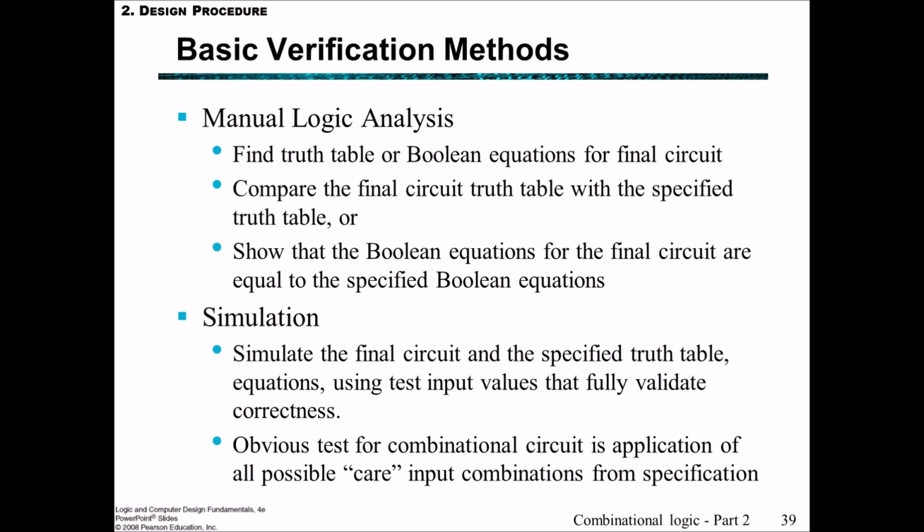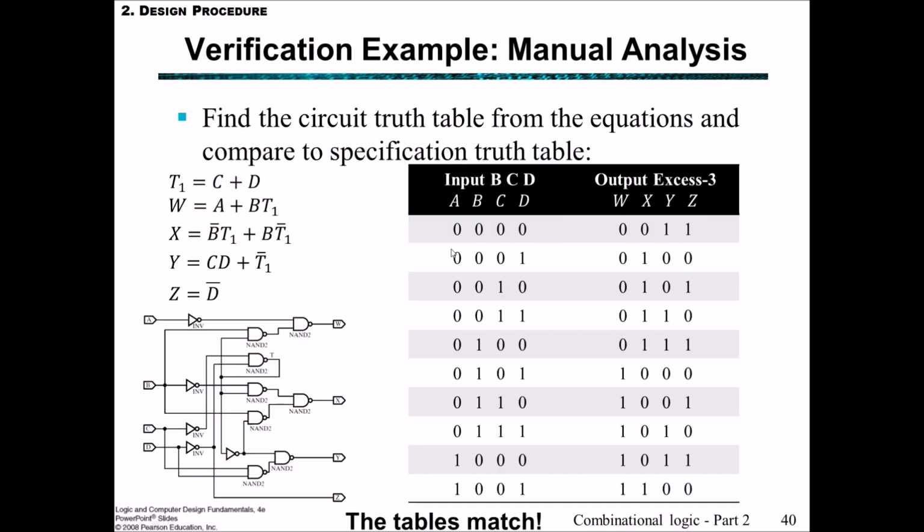And obviously, we don't have to include don't cares. It's only testing the combinational circuit for applications of possible care input combinations. That is, in our case, from BCD to XS3, it's from 0 to 9, and they're the ones that we actually care about getting a correct output for. So I'm not going to go through every single one of these, but I suggest if it was something simple like this, that it's worthwhile doing that yourself as an exercise. I'll pick out a few to trace through.